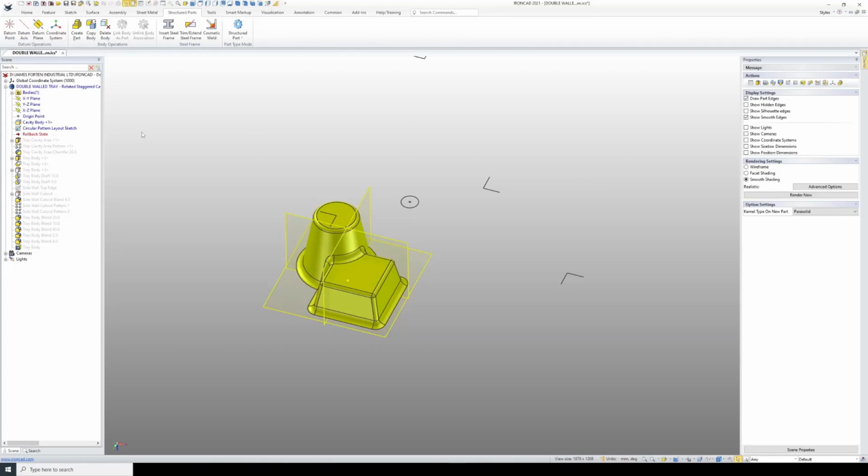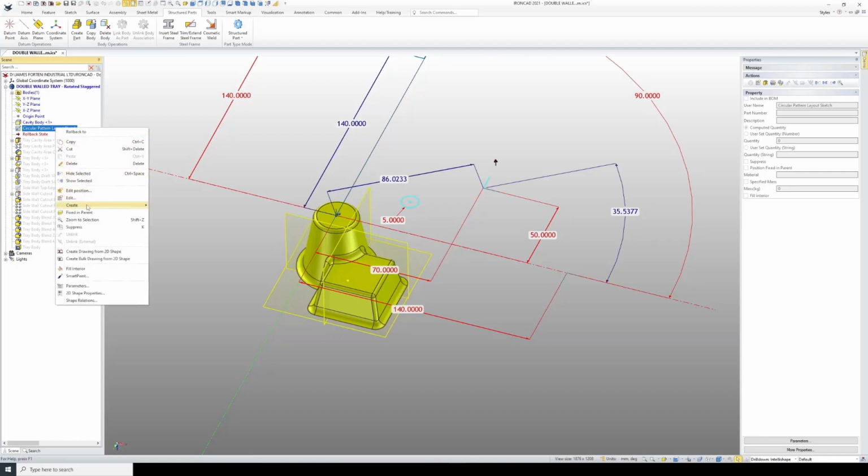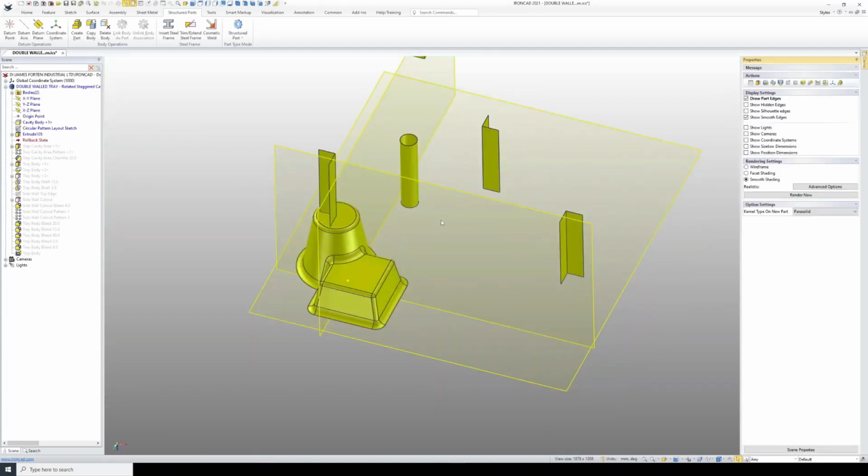But we're going to use extrude a surface body just for demonstration purposes. So with the sketch selected, right click and create an extrude. Now instead of extruding a solid, because the sketch consists of open paths or open lines, we're generating a surface, and so that's what's selected as a surface over on the right. Now it's extruding upwards 50 millimeters. The height's not important, and even the direction is not important. So if it's extruding up away from the part, then that's fine.